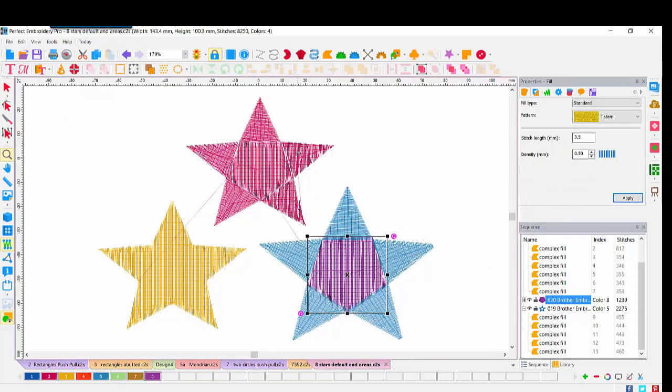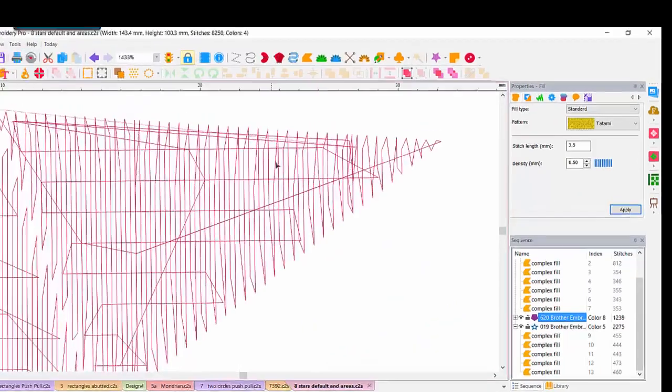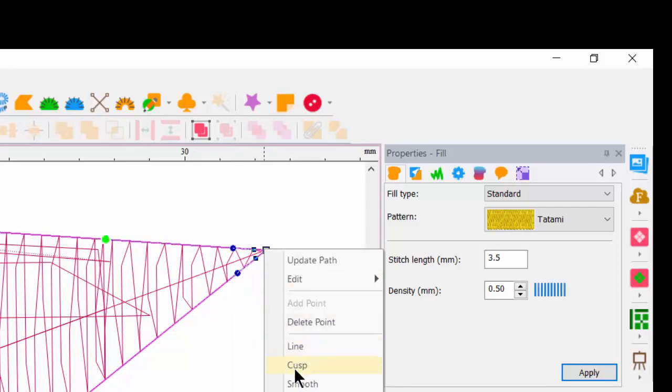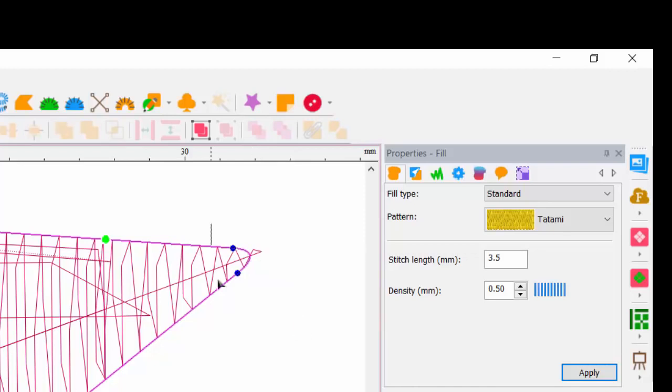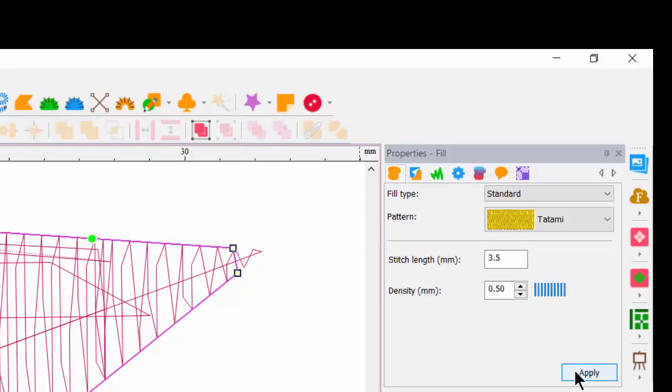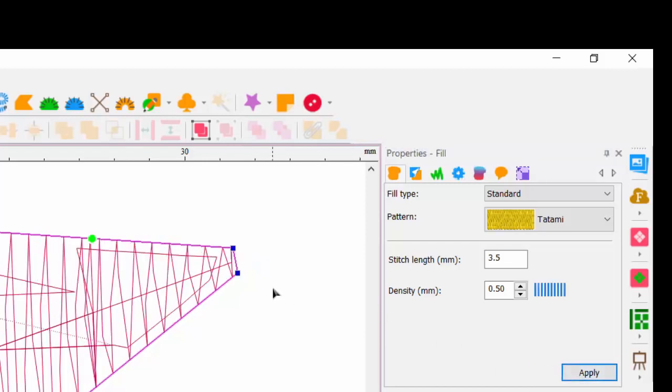We'll zoom in on this particular point, select this area of the star. Again, there's that exact point. A right click, add that point. A right click, add that point underneath it. I will select this one at the tip and I'll do a delete, and then I simply drag around both of those and I made them align and applied, and that's how I rounded off my points.